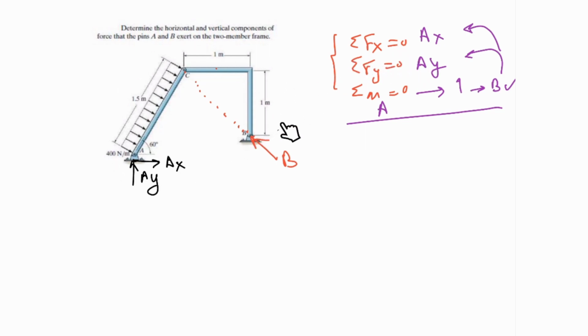Finding the 2 force members is critical. If you're facing a problem like having more unknowns than the equation numbers, you need to get back and have a look at the diagram and the free body diagram that you have, and try to find 2 force members. That would be very helpful.